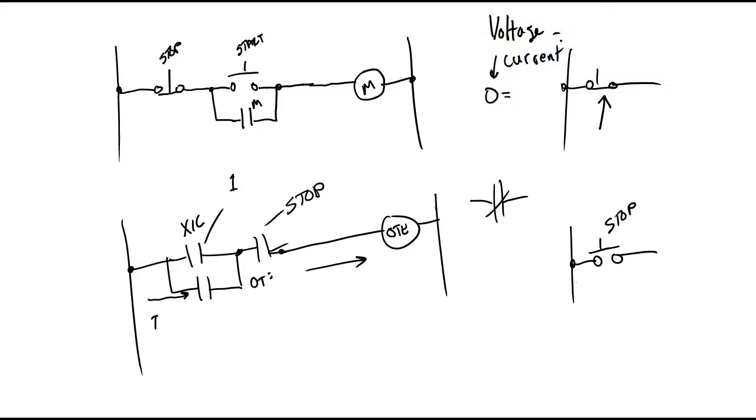Now, what advantage does a current have over a voltage? Well, current's going to flow either way. If you have a voltage and you've got resistance, you're going to have a current. Usually when we use voltages, we use very low current. The problem with using voltages is electromagnetic interference can change voltage levels. So voltages are susceptible to EMI. Currents, it's real hard for an EMI to change current, right? You understand? So we have something called a 4 to 20 milliamp current loop.